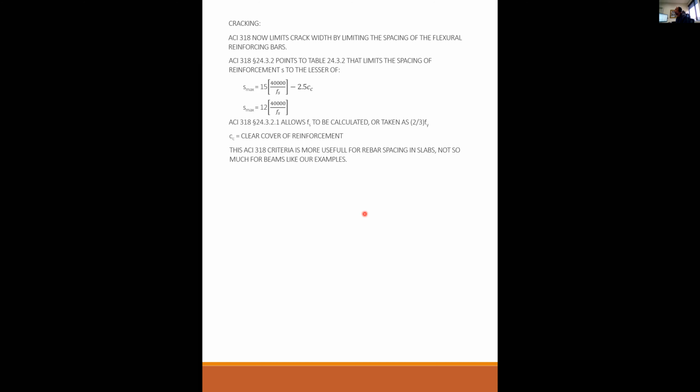Okay, the other thing that I noticed a lot of students doing, and maybe I didn't cover this clearly, but I want to talk about it now, is that in some design problems, you don't know the steel and you don't know how deep the beam is. So I gave you tools and techniques to derive, based on the load that it's supposed to carry, how deep d needs to be.